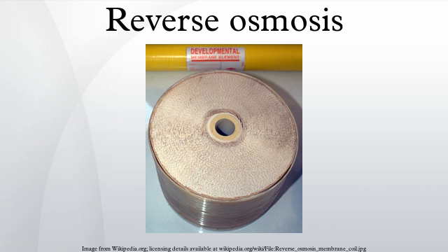The material is engineered in such a fashion as to allow only one-way flow through the system. As such, the spiral wound design does not allow for back pulsing with water or air agitation to scour its surface and remove solids. Since accumulated material cannot be removed from the membrane surface, systems are highly susceptible to fouling. Therefore, pretreatment is a necessity for any reverse osmosis or nanofiltration system.